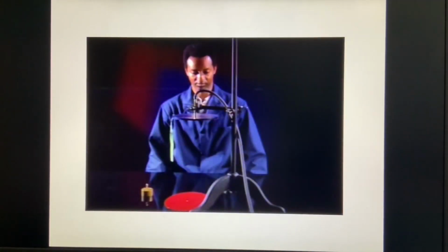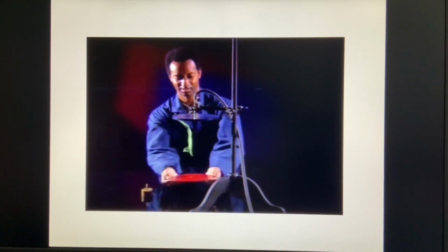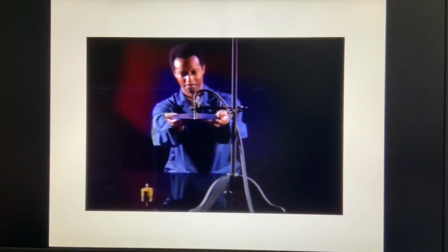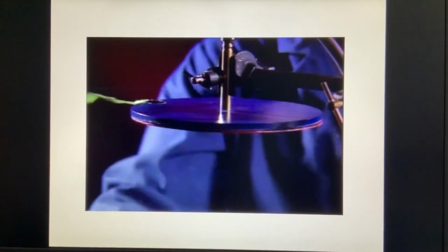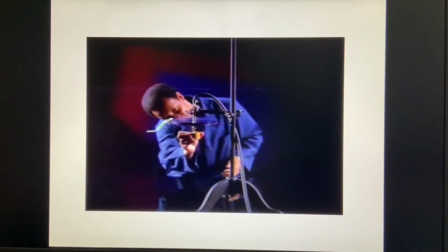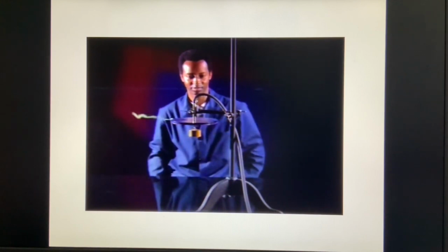If we blow air through the hole in the center of this disc, light objects such as this streamer are blown away from the disc. If we put a second disc up to the first with the air blowing, what will happen? The second disc is pushed up against the first because the air moving between the discs is at a lower pressure than the air beneath the lower disc. Even if we attach a weight to the lower disc, it still hangs beneath the upper disc.